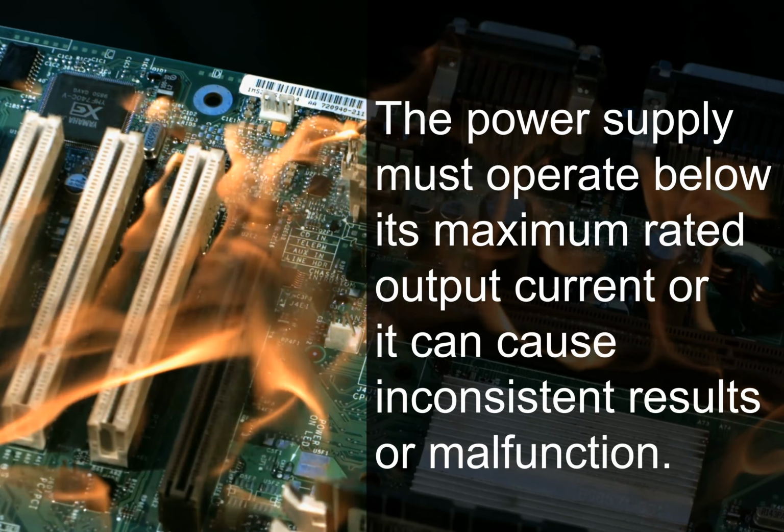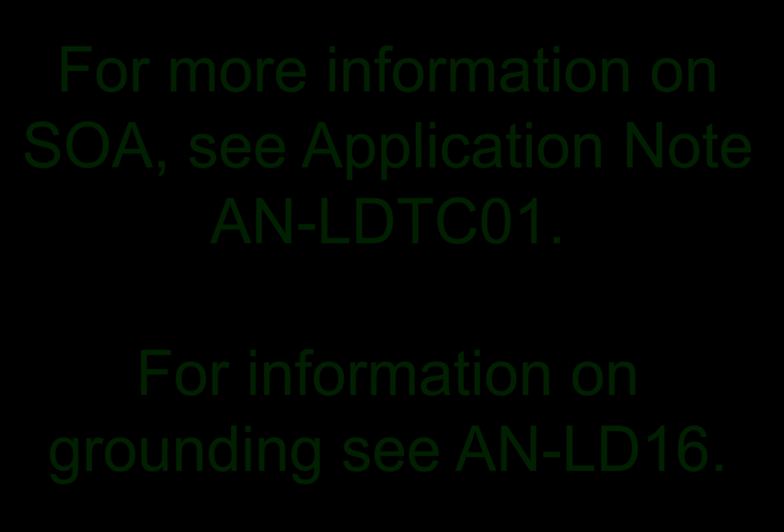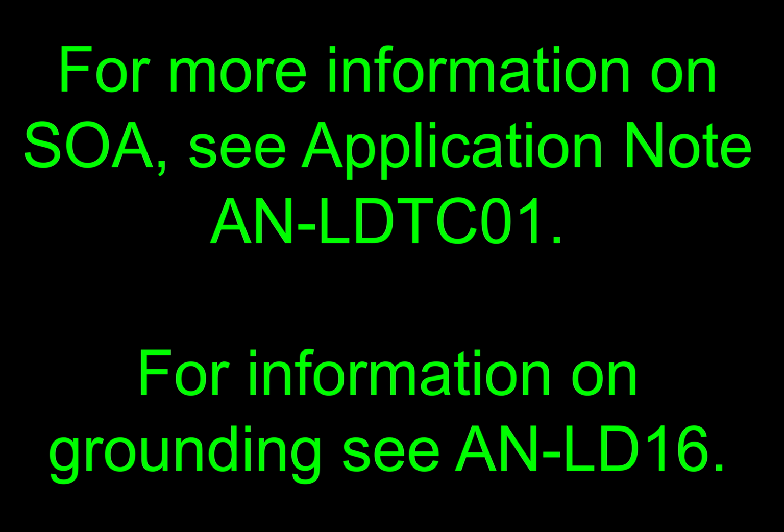Can I use the same power supply to drive my temperature and laser controllers? Yes, as long as the voltage selected meets the needs of the load and is within the safe operating area of the controller, and the laser thermoelectric and temperature sensor are not electrically tied through ground. For more information on SOA, see the application note on our website. There is also an application note on grounding.